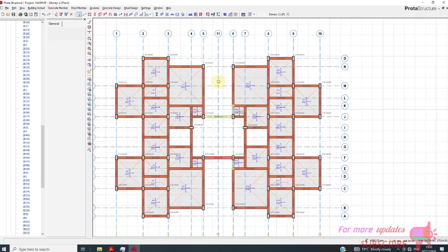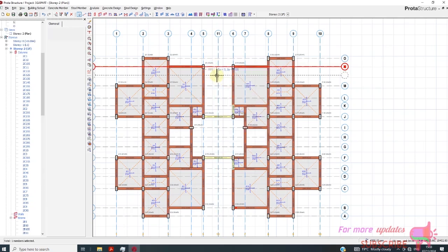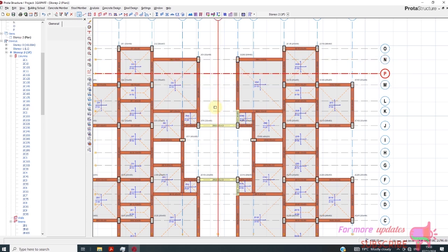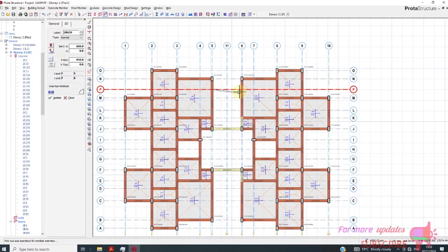So I can just offset this by a distance of about, holding F2, negative about negative 12 or 1000. Enter. Then escape. Then I can add another beam from there.